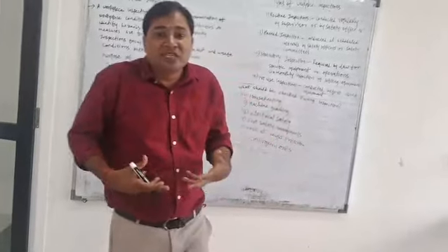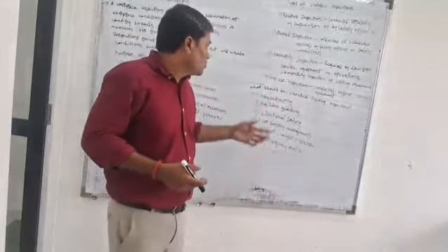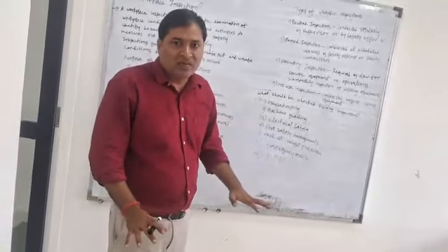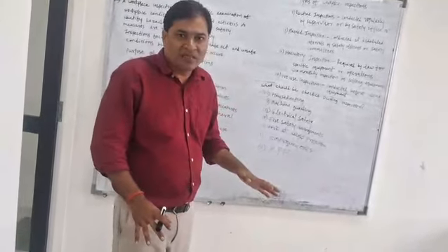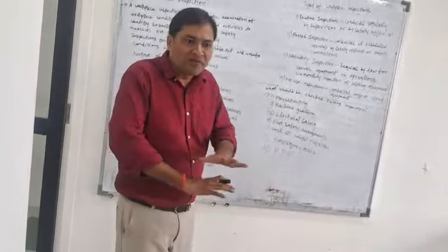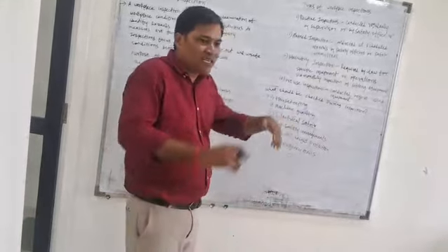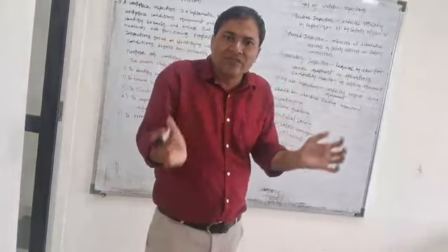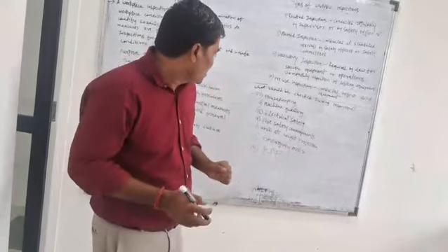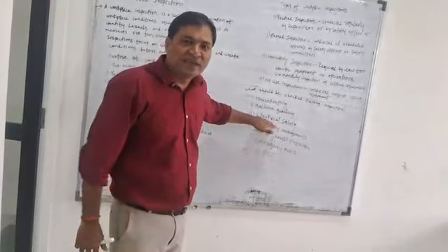What should be checked during inspection? What are the things which you need to check? That is very important. So first we need to check the housekeeping, the area which is totally clear. Okay, it is not a dirty place. There is no oil spill, nothing, no electrical short circuits. You have to check the proper housekeeping and the hazards as well. Then machine guarding, there should be a guard on top of the machine. Every machine should be guarded. Okay, there should be nothing open-ended.